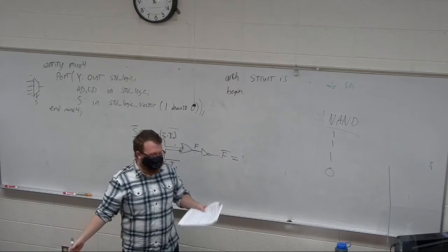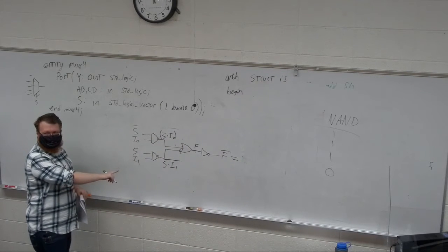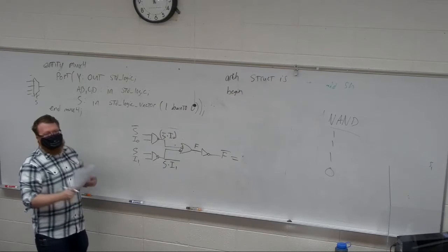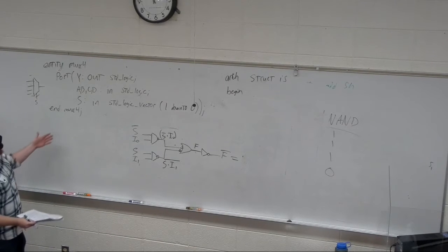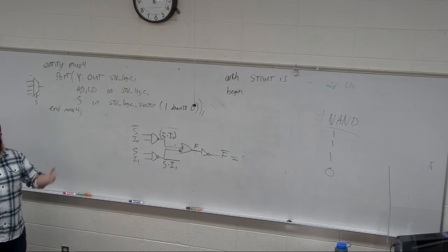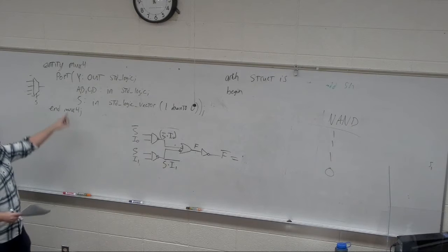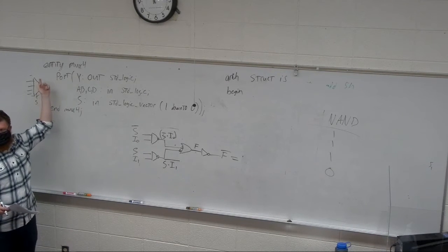So what is the structure of a mux? Well, it's just this, right? So I can do a couple of different things. I can say if select is 0, then f, or in this case y, is equal to I0 or whatever.